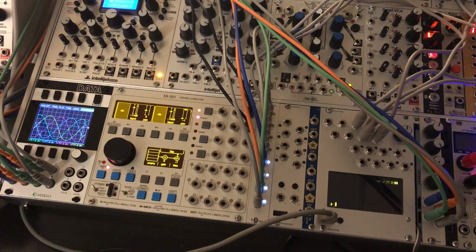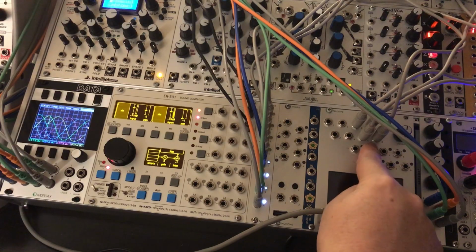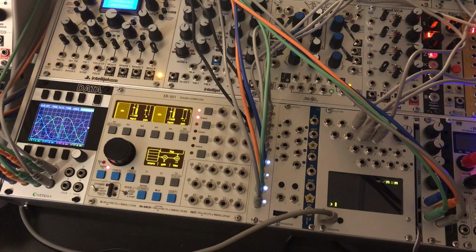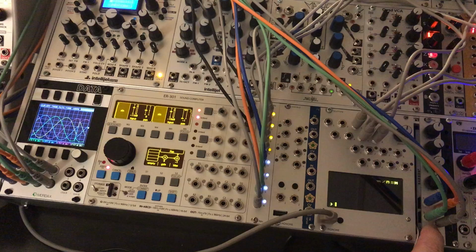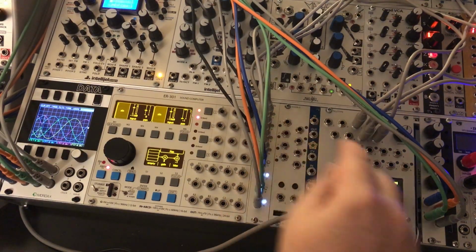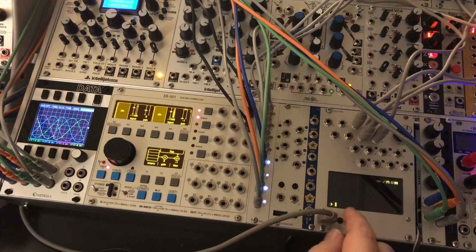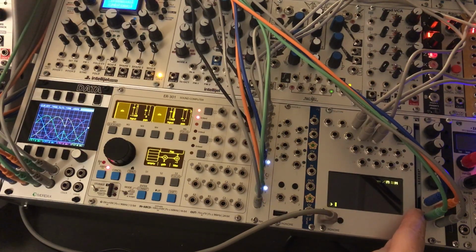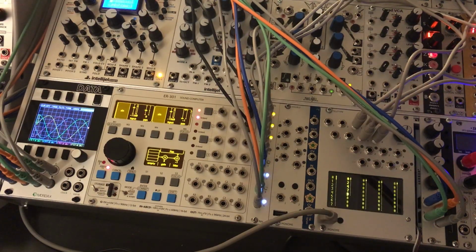The trigger outputs here are being fed back into the Teletype over here, into the 5, 6, 7, and 8 trigger inputs, and those are triggering different scripts. The 4 CV outputs are being fed back into the TXI. Essentially, every time one of these gates fires, a script fires, and we are grabbing the value of that LFO that's being fed into the input expander. We're doing a sample and hold operation, and we're also using that to quantize to a custom scale that we've defined over here.